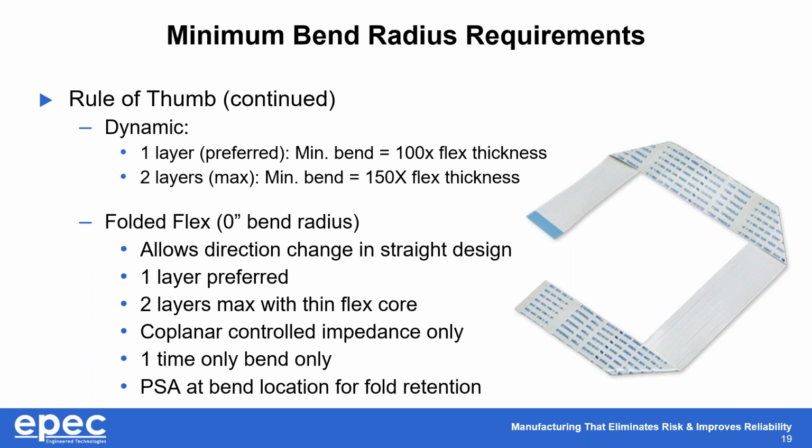It is, without exception, a one-time and one-time only bend. When you bend it, the copper within the circuitry layers becomes deformed and elongated as a metal. It starts to work harden and embrittle. It hasn't broken, it's still fully intact, but it has lost a significant amount of its ductility.